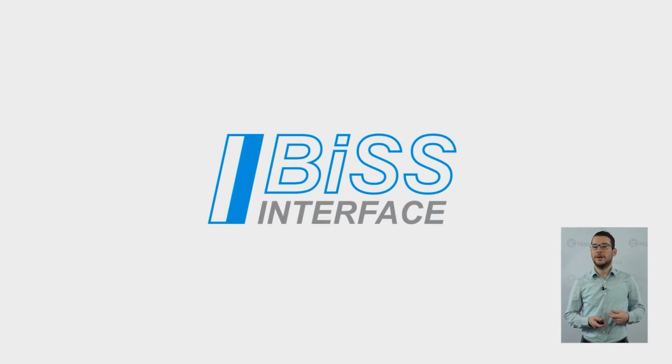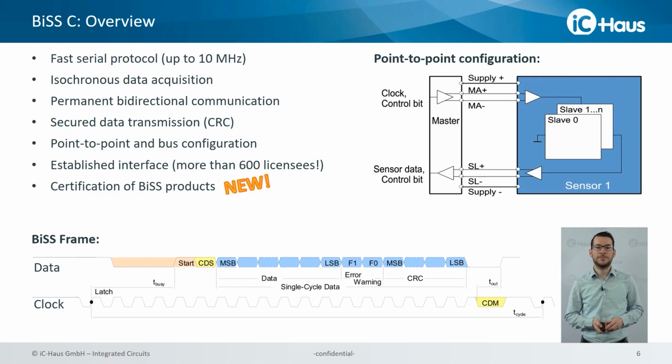So now let's take a closer look at the BiSS interface. The BiSS interface protocol is already established and enables high-speed isochronous process data transmission. For today, we do not go too much into detail, but we focus on 2 aspects. One is that in point-to-point configuration, we need at least 6 wires: 2 differential pairs of wires for the differential clock and data transmission, and 1 pair of wires for the power transmission.